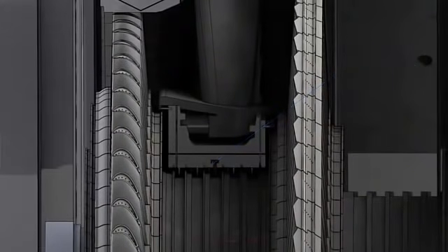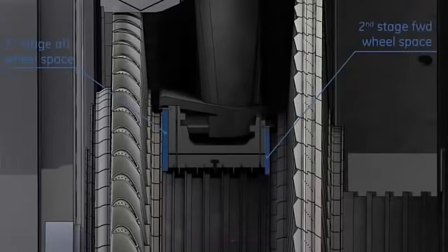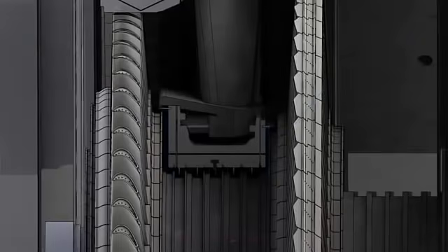A brush seal segment is installed on the inside diameter of the diaphragm between the labyrinth seals. This brush seal is in continuous contact with the turbine rotor spacer surface to control the amount of the cooling air passing from the first stage aft wheel space to the second stage forward wheel space. This ensures more precise cooling and better unit efficiency.